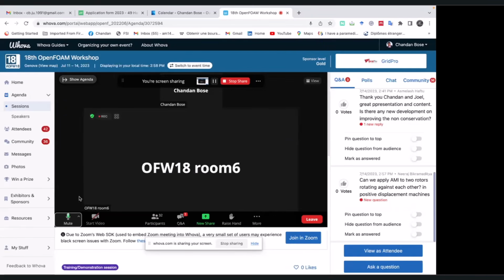No worries. I just have a question on the overset mesh interpolation schemes. If you go to them, it says that the inverse distance and the least squares were second order. Now I've been using overset mostly in foam-extend, and when I use the inverse distance scheme, I only get first order convergence. So if I'm using a second order interpolation scheme, should I get second order convergence from the solver? I see.